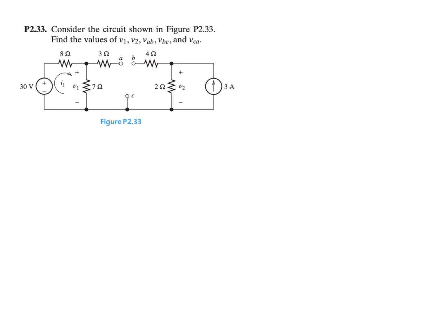Well, first you will notice that A and B are not connected. There is an open circuit. That's the second type of situation we discussed. So in this case, when this is open, there is no current flow. I is equal to 0. No current flow means there is no voltage drop between point capital A and this A here. And similarly, there is no voltage drop between B and this B here.